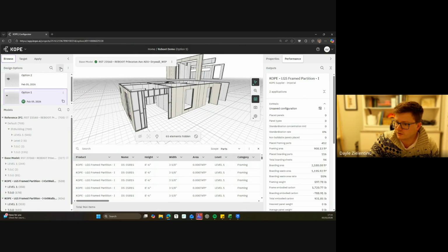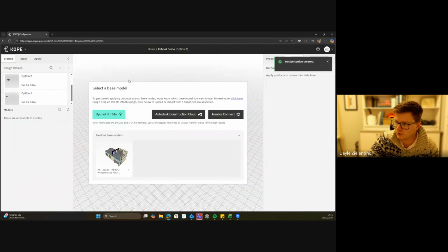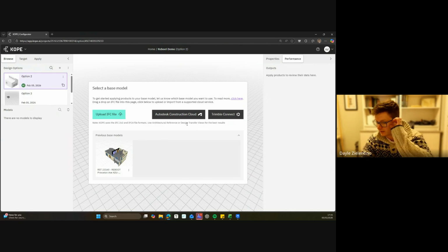Yeah, that all happens in Trimble. So obviously Tekla is owned by Trimble. So what you can do is actually pull from Autodesk's ACC cloud. So actually pull IFC files directly from there, or you can pull Trimble files or IFC files directly from Trimble Connect, and we can push them back up as well. So we can push them directly to those cloud spaces.